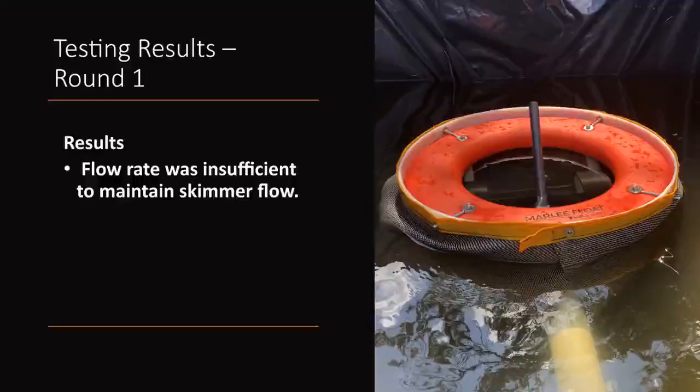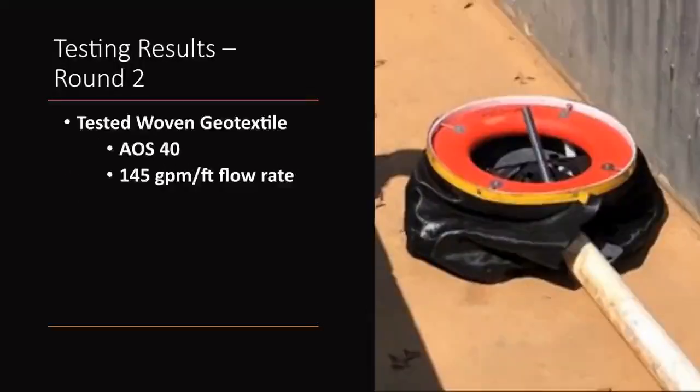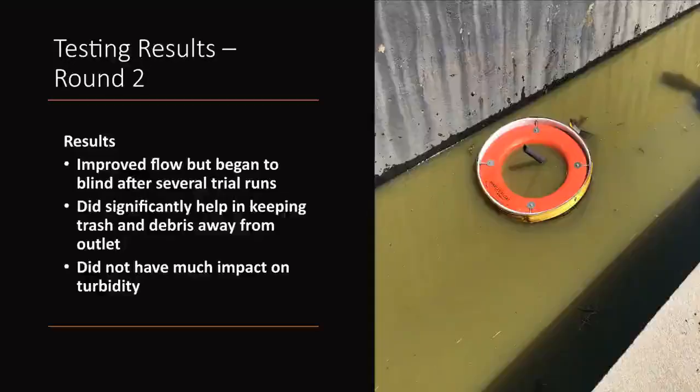The results from our round one determined very quickly that this flow rate was insufficient to keep up with and maintain the skimmer flow. Our second round of testing also tested a woven geotextile, had an AOS of 40, and a much higher flow rate of approximately 145 gallons per minute per square foot. This testing improved flow, but began to blind after several trial runs. It did significantly help in keeping trash and debris away from the outlet of the skimmer. It did not have much impact on turbidity, as you can see from this photo, as the water inside the filter and outside are essentially the same.